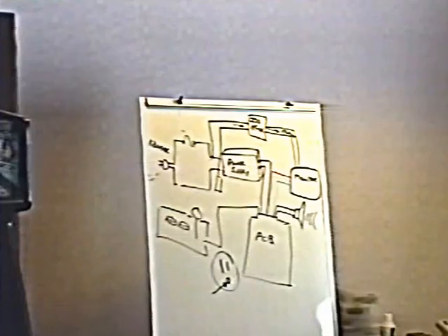There's another type of power supply made by a company called Hytron. It's actually a very excellent power supply. And here again you see AC-AC. What they call ground is frame ground, the FG connection, same thing. Their regular ground they call DC common. See that? DC common is the same as ground is here. Ground down here is the same as FG here. You can see they're in the same position and everything. I know it's a bit confusing. It was just a matter of terminology.